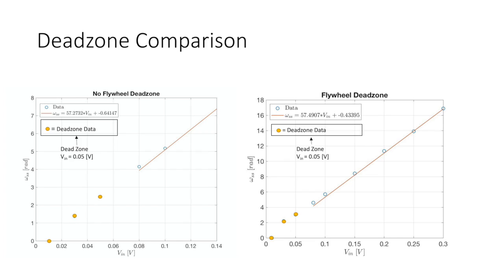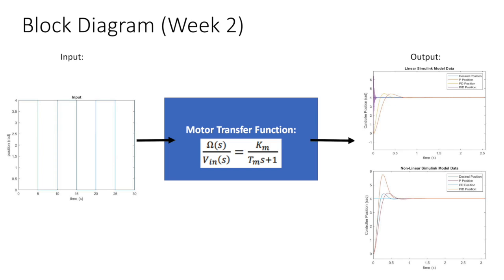From the Tm and Km that we determined, we can use them to determine the gain constants of Kp, Ki, and Kd for our PID motor control. The block diagram shows the Laplace transfer function relation between these constants, the transient response previously identified, and controller output to a desired position for the motor that was specified by Quanser Inc. Now Brittany will help to conclude everything.